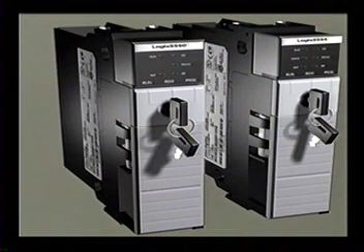So first we have the CPU, and again you've got your key here. When it's in the middle position, it's in the remote position. Here's your program position, and here's your run position. So what you want to do is, after you've got this thing up and running, you're on the factory floor, go ahead and put it in run mode and pull the key.